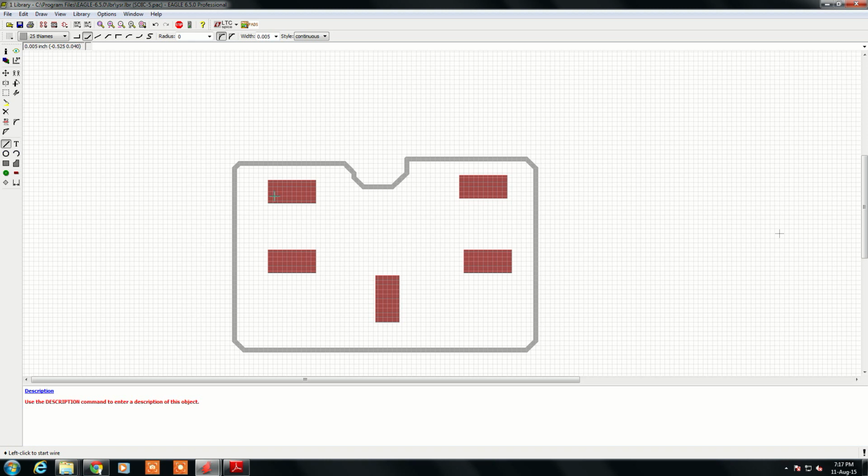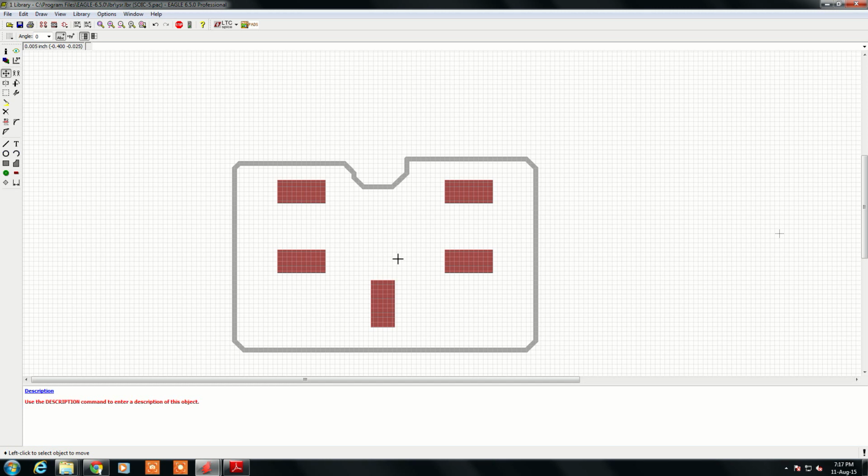So once this is done, even if you want to make any minute adjustments after taking the printout, you can always do it with the move command. You can move your pads because you have designed these pads. So I always suggest take the printout of this first, place the component, and accordingly adjust the actual size of it, because we do this once for all, not every time.